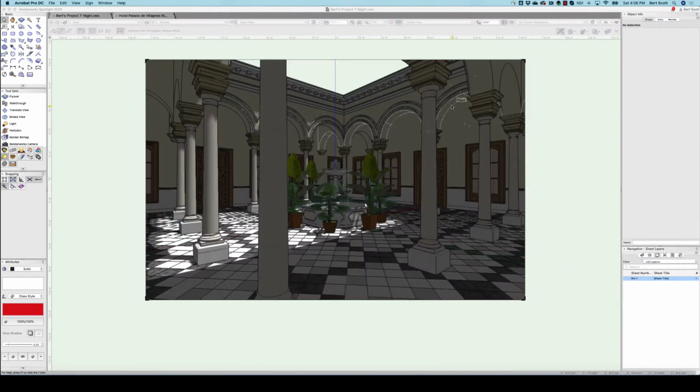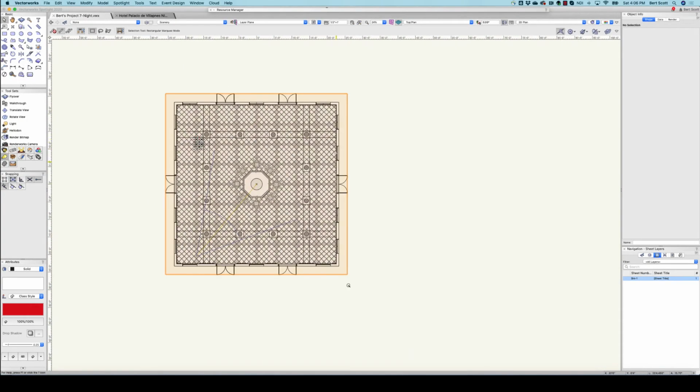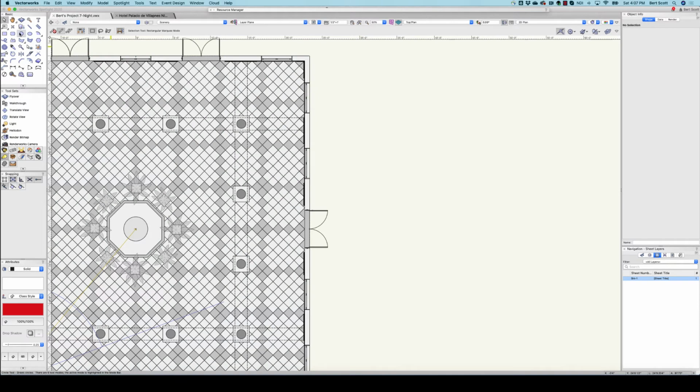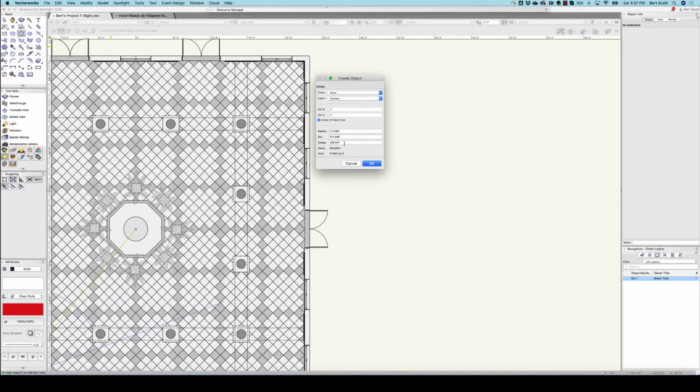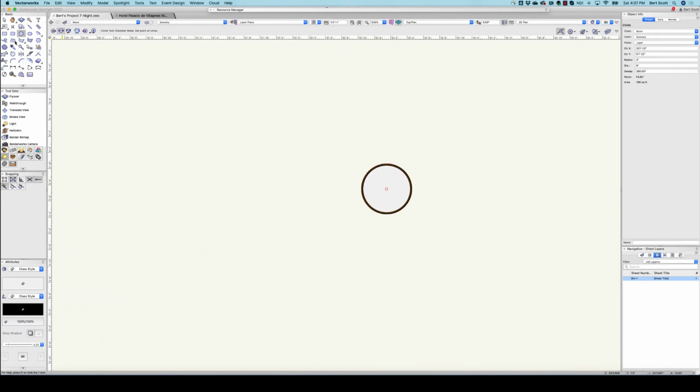So I'm going to go to top and draw a circle that's 6 inches in diameter, and then use the offset tool. This is a metal can, so I'm going to offset it by like 0.1 inch.